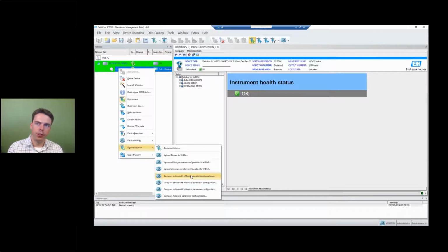And I can also store this information in digital format in the database, which enables you, if you have to replace the device with the same type, to just connect it, get this data assigned to the tag, download it and load it into the device. Then you would have restored the whole device configuration with just 2 clicks. This is also a very useful tool for maintenance, to troubleshoot and to do device replacements. Also, configuration reports can be stored there, and you can access the information.